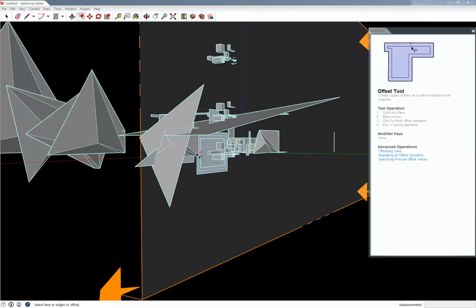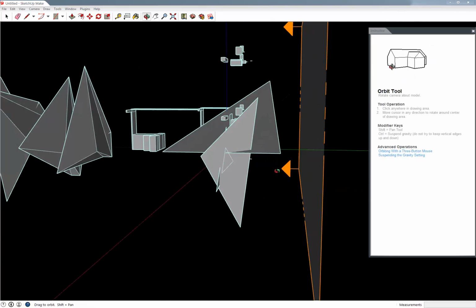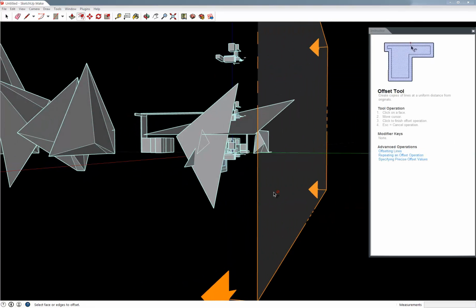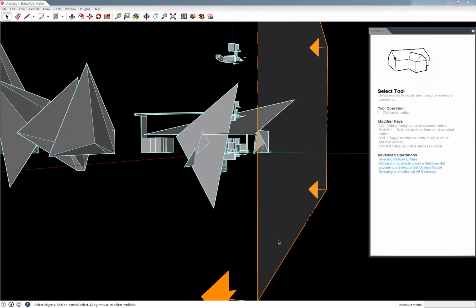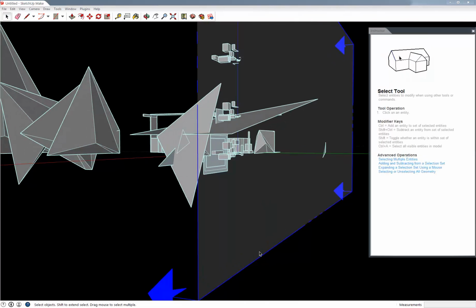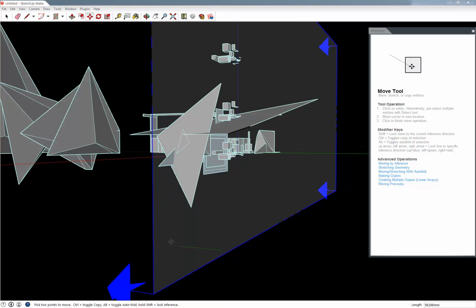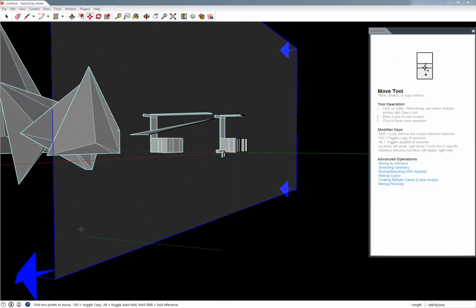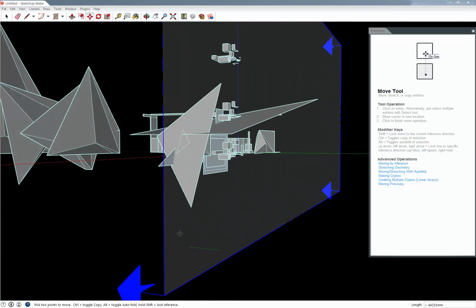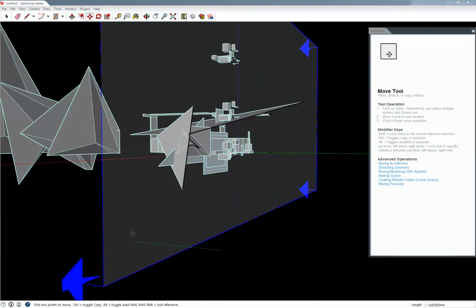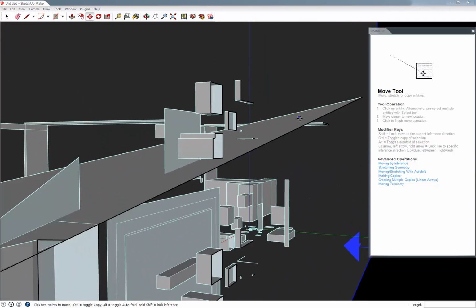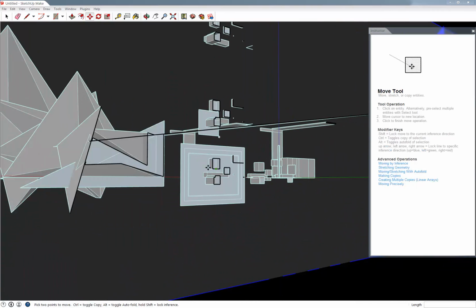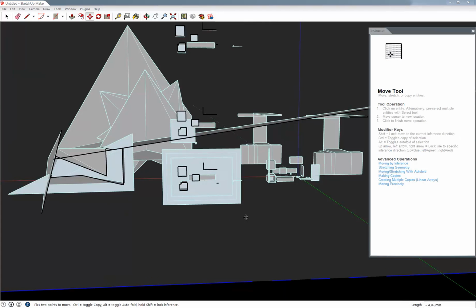Click on there, draw the section at that point, and it's put me back into the last tool I was using. So I'll press space to select. Now select the section plane, so you can click on those arrows, or the actual plane, and then press M, and I can move it in and out. So you see what it's doing here. It's hiding everything behind the section plane. So I can go like that, yep, I want a view like that, so now I can get this section view of what's inside here. You can see what's going on really easily.